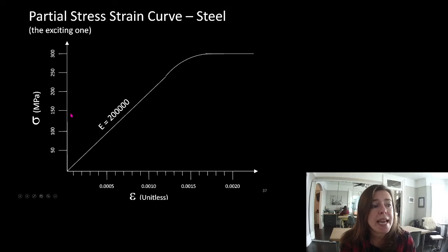So we can calculate what the stress is because we know what our object is. We know what our cross-sectional area is. We're testing this object. We know how much load is on it because we're the ones applying the load. We know how much it's deformed. It's empty because it fell over. We know how much it's deformed because we're measuring how much it's deformed, which means we can plot these things against each other and calculate E.